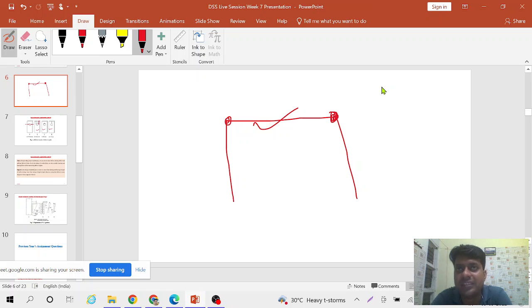If we have designed our section as under reinforced, then what will happen? First of all, your steel will show the deformation, means your steel will reflect that deformation is coming, so you can see your members bending or deflecting with your eye, and it gives you an alarm before the failure. But what will happen in case of over reinforced section? Steel will not fail first, your concrete will fail first. So when concrete fails first, no sign or alarm will be given, so directly your member will fail. So that is why we prefer under reinforced section.